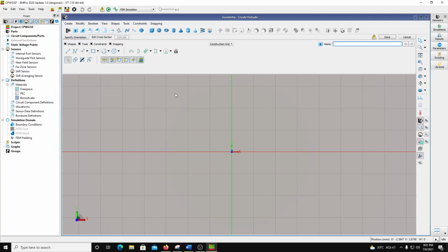If you refer to this video back in time, you will see that the object was drawn at a certain height. We will try this attempt again, but for now I'm trying to teach you how to draw directly in EMPro. These are the snap options: snap to grid, snap to intersection of grid with the edge, snap to corners, snap to edge, snap to intersection of two edges, snap to cross section. So these are your snap options. Very simple. On metal 6, if I want to draw, I will start with 0 0.